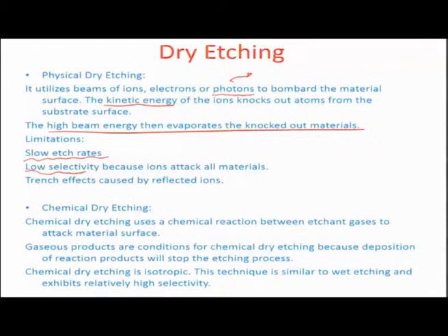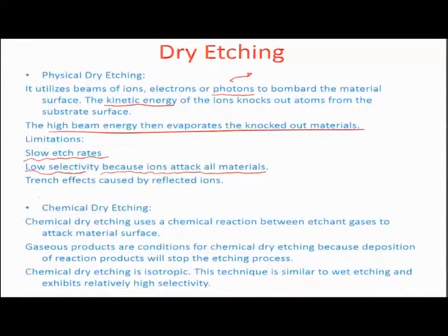But in this case, because of the ion attack and the rebounding of the ions, whatever is being attacked by the ion would have some kind of thermal energy and a melting or vaporizing aspect. So, there is not much selectivity unless there is masking or shielding offered through a shadow mask, which I will come to later when we talk about lithography processes. There are these rebounded ions, or maybe electrons, which are able to etch the surface, but probably not to that level of roughness.